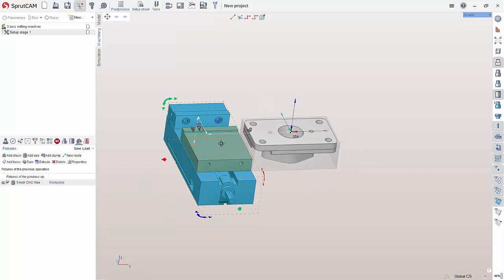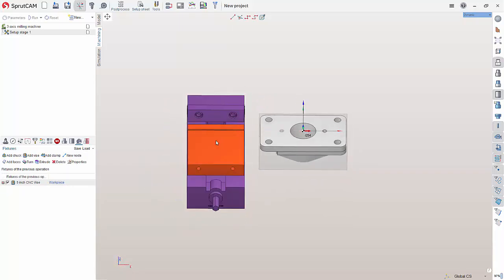Now, this is what I would recommend doing. I would choose this "to machine" option to start off with. This is going to basically snap the vise to the machine instead of the workpiece. So when we go to move this around, the vise doesn't move with it; it's going to stay locked to the machine.